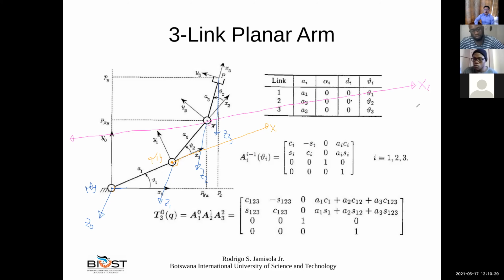Remember, there are two conditions. One condition is perpendicularity, or normal to both z1 and z2. That's already satisfied. But intersecting z2 and z1 was not satisfied. It intersects only z2, but it didn't intersect z1. Again, we need to rotate. We rotate here so that your x2 becomes that, and the whole line is this. The negative x2 in this direction.